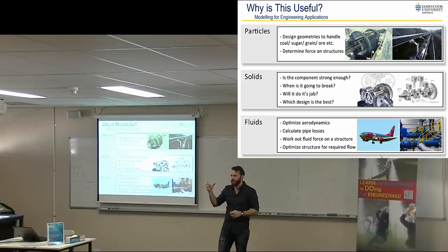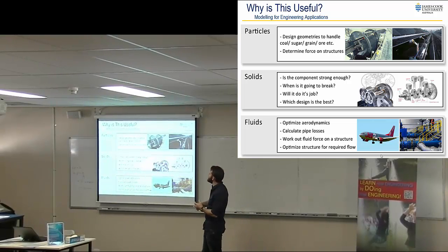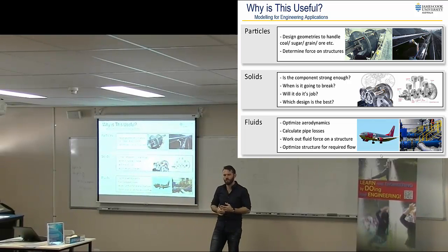But the same way that if you had a Coke bottle full of wet sand rather than dry sand and turn it upside down, it all gets stuck. So that's called cohesive or mechanical arching, depending on what the circumstance is. You find that they have a lot of coal getting stuck in these things when they try to use that type of technique. And a lot of the unloading stations that use those will have these massive big jackhammers that come and shake the bejesus out of the actual carriage to try and get the stuff out.